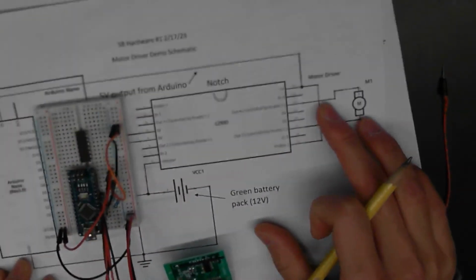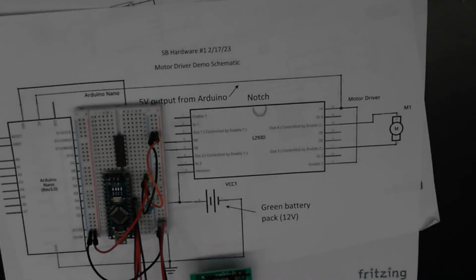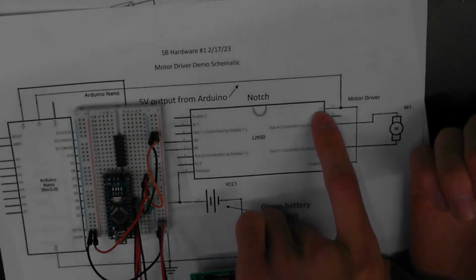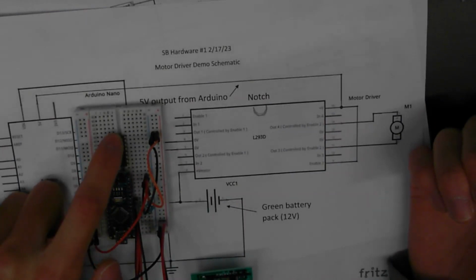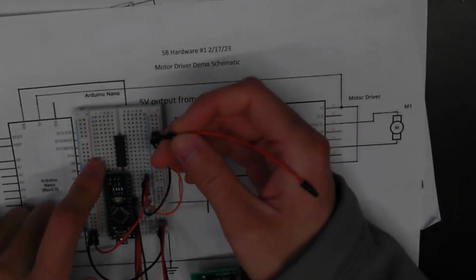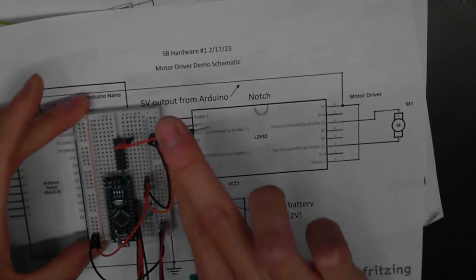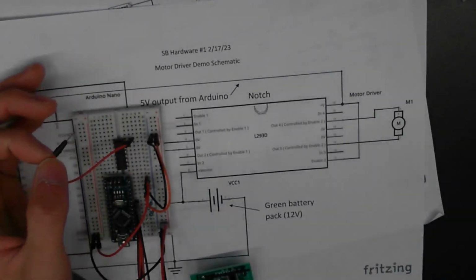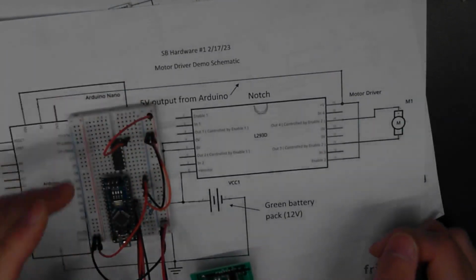Okay. All right, so let's start with connecting the 5 volts to the motor driver. This is to bring power to the driver. So that would be on the schematic the plus V, or pin 16, or in this case, the top right corner of the chip. So we take our lead, connect it to that row, and then this is our 5 volt line. Remember, the right side is 5 volt, the left side is 12 volt, so we connect it to the 5 volt side, just like that.